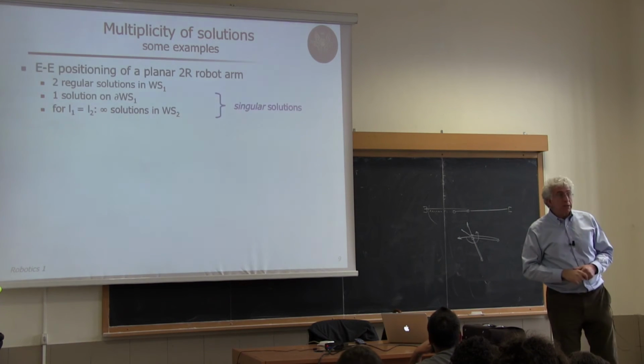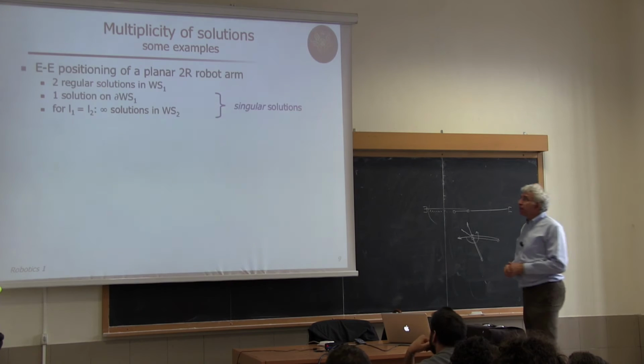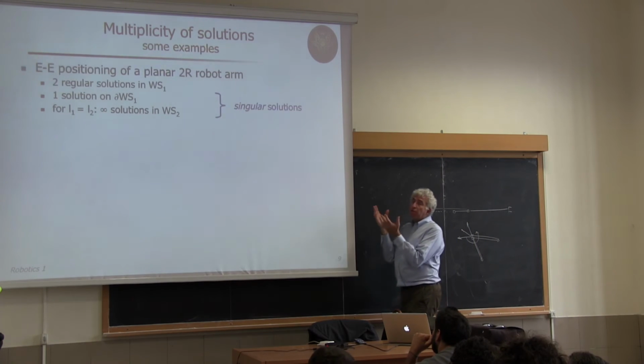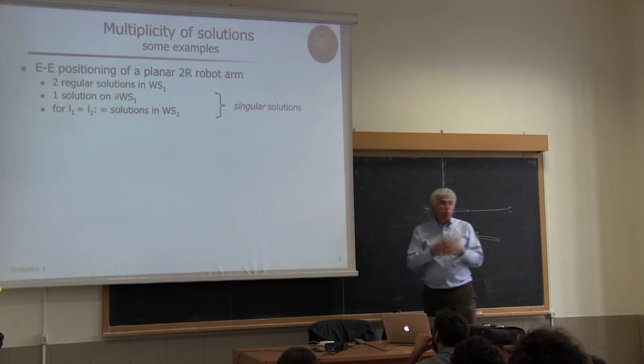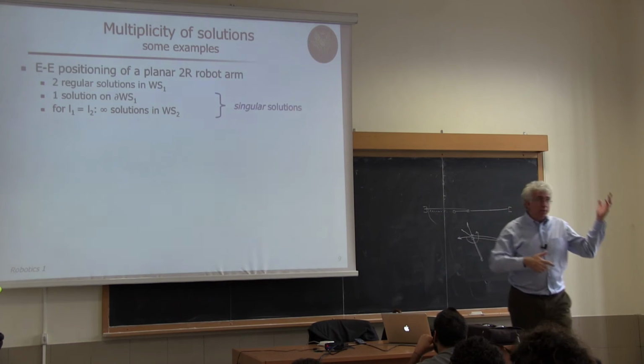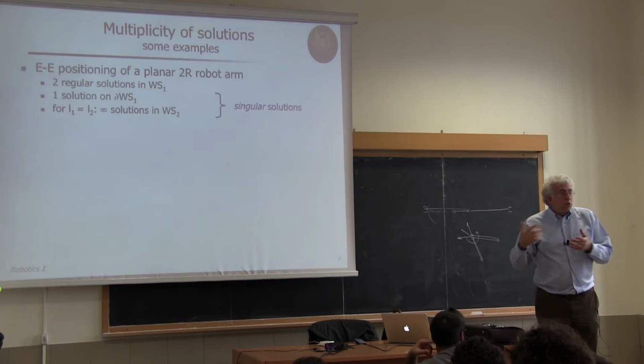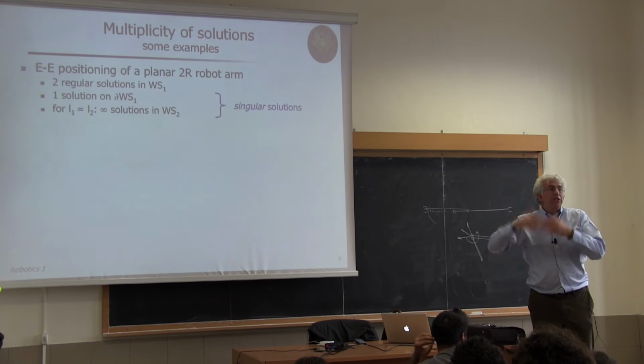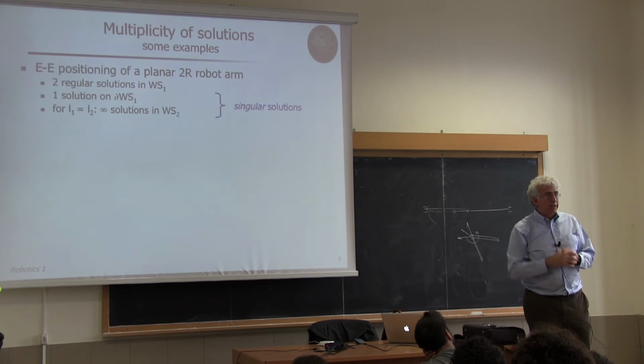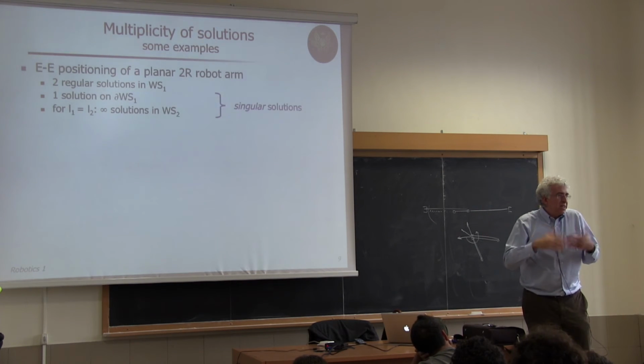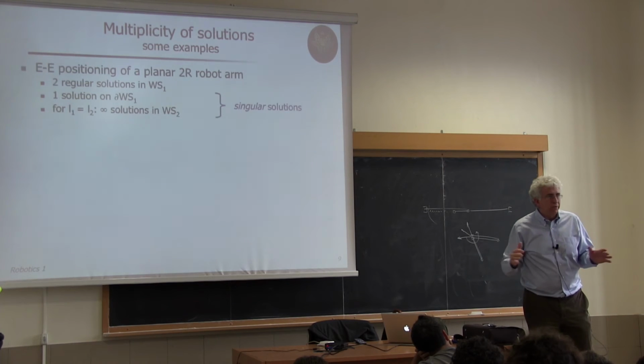But those special cases are called singular because the number of solutions is different from the regular one, either 1 or infinite. Well, you could call singular also the case where there is no solution because I'm giving a point outside the primary workspace. But this is not of interest. There's no solution. Full stop.